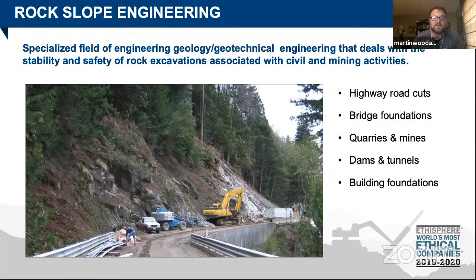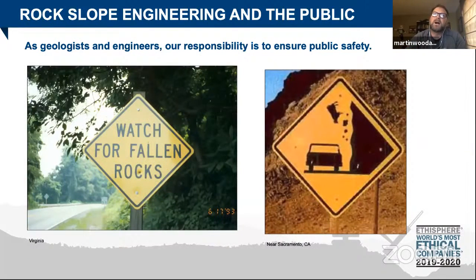I've been in dams and tunnels, and I've even used rock slope stability to build infrastructure underneath existing buildings. If anybody remembers Rocky going up to the Philadelphia Museum of Art, we used rock slope stability tools to actually blast and tunnel underneath that museum. Quite interesting. So those are the areas where you generally deal with rock slope engineering.